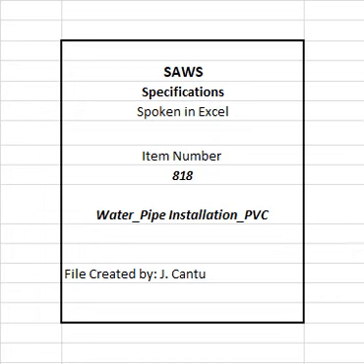4. Testing plan, submit at least prior to start of construction and at minimum, include the following. 1. Testing dates. 2. Piping systems and section, s, to be tested. 3. Method of isolation. Method of isolation to be approved by SAWS inspector. 4. Method of conveying water from source to system being tested. 5. Hydrostatic leak testing.